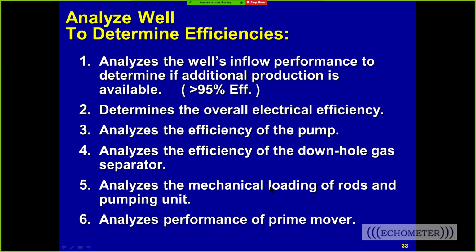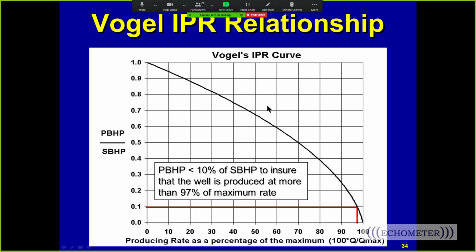Is the mechanical loading of your pumping unit exceeding the rating of the equipment? And is your motor being thermally loaded? Is it going to burn up? These are all the kinds of things you can use to analyze your well.